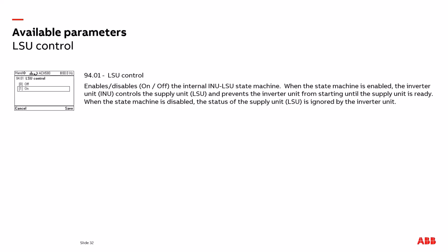If you turn it off and you go in to try to do some programming, you won't be able to send information over to the line supply unit. The default is on, so we leave it on. When the drive is powering up, the status of this may change because certain things are happening, but it will go back to its original setting.